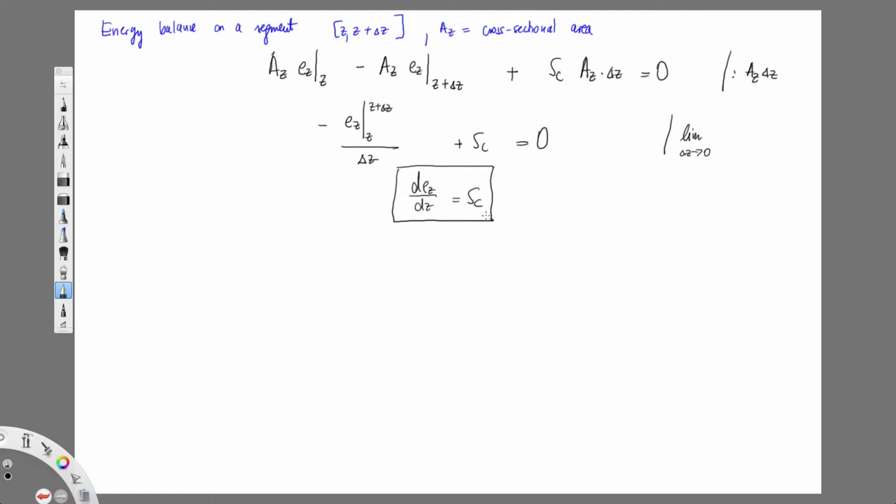I love equations that look very simple, and then you start solving them. So now is the part where the equation looks super simple, except that we didn't write down what E_Z is, right? So once I actually write down my combined energy flux, its Z component is 1/2 rho V squared plus rho H, so enthalpy per volume, times V_Z, plus tau_ZZ V_Z plus Q_Z.